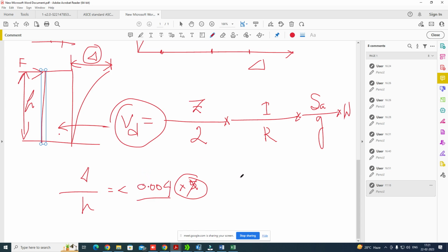Now suppose I want to check for other cases. This I have satisfied. Let's say when I check this drift ratio, this is satisfying the criteria. Now you are going to analyze the structure for the pushover case, let's say. So you can again check the drift criteria, but that should not be satisfied with this value in case of pushover.